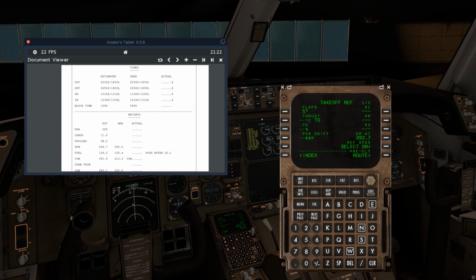So you take the 5 degrees, you look at your pressure altitude based on the airport elevation, your temperature, dew point. You go to a performance chart and it gives you a temperature, and that's what you enter right here on the FMC. That lets the engines make less power than they need to, to reduce wear and tear. We're not going to do that. We're going to keep it simple. So I'm going to use 5 degrees. We'll put that in, and it is saying it's derating, so we'll save a little bit.